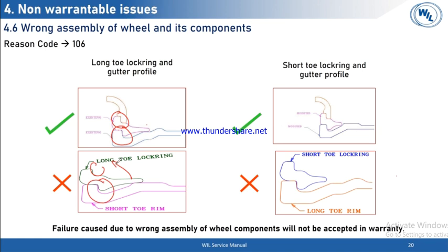Understood. Sanjay, please arrow this toe. This is more critical. This is what I'm saying. The graph is like this. So this gap is important. Whenever we put the tire pressure, the tire pressure will act on this area. So this will get lifted like this. So the toe will get lifted and this will come out. If we use the wrong kind of lock ring for the particular wheel rim and do the tire assembly at a puncture shop, then after air filling, this will come out.